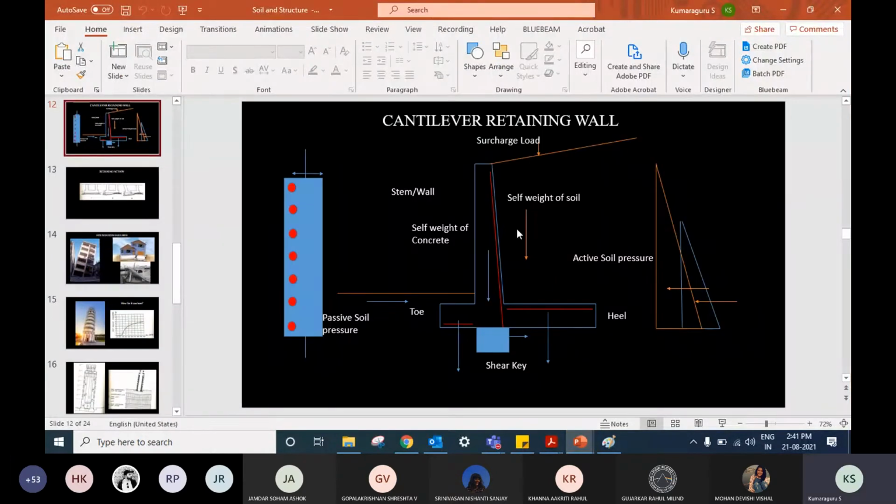What essentially we saw right now was we just designed this vertical tension rebars. Okay, so we need to just put a minimal rebar on this face as well. Similarly, there is a cantilever bending moment, which is experienced by this particular member here and this particular member here. So for all the cross sections, whatever the forces, whatever the bending moments it is experiencing, we need to figure out what is the rebar that we need to put.